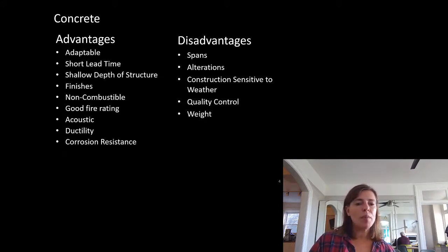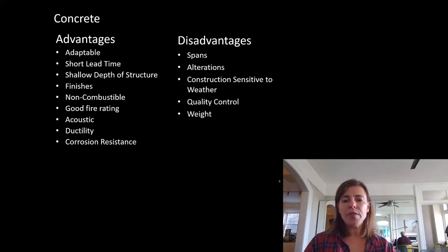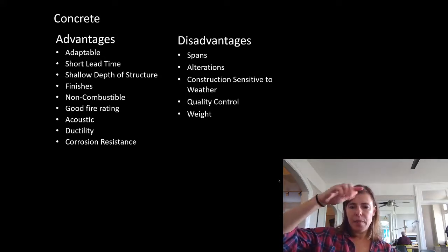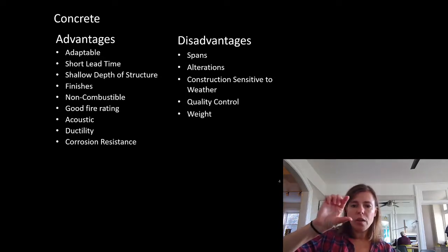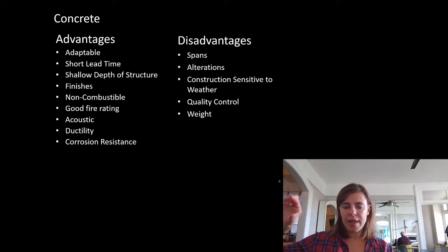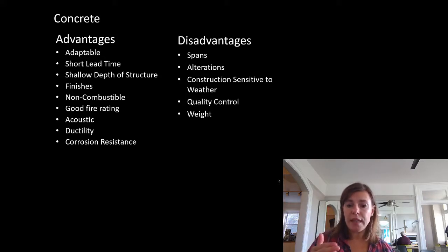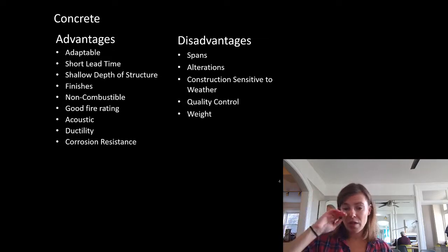And normally this is where I draw out a few things. It's a real disadvantage that I can't sketch things out for you quite quickly. But often, in a steel building, we would have a beam that's deep, and maybe we go along where our deck is, and then we have a joist, and we go along and we have a joist. Concrete could be consistently all that deep. So steel locally might be quite shallow, but often we put a soffit or a ceiling under there that gives it the illusion of being much deeper.